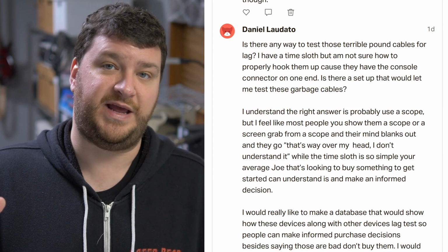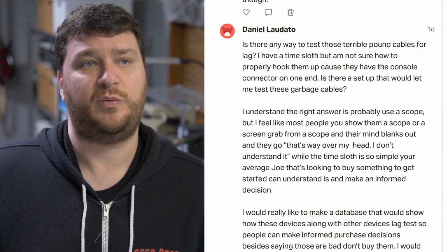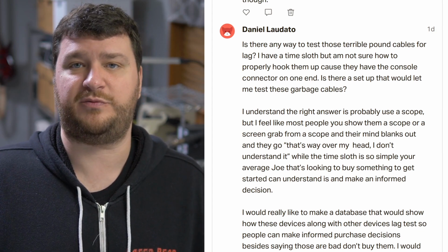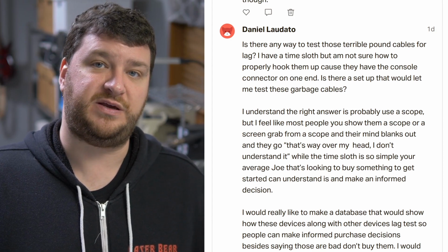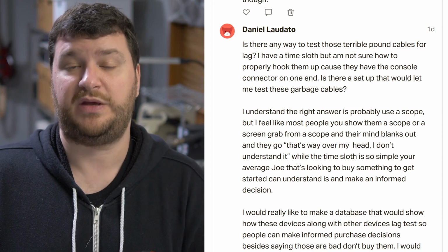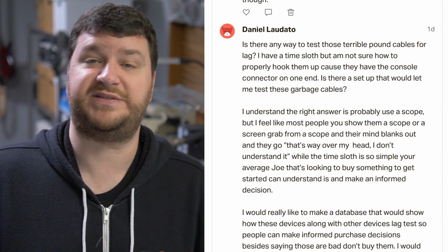Then you need to take an SNES style multi-out, the jack version, not the plug version, which there are open source designs out there that you could easily pick up. There's a bunch of different ways that you could do this, but you have to get one of those and you wire RGB from the HDMI to VGA converter directly to it. Then you take H and V sync from the VGA converter and put them through a sync combiner.